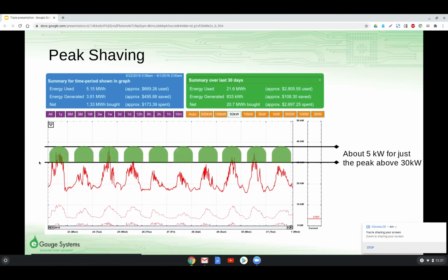When you're designing the system, you can decide whether you want to cover just the peak, where this is probably going to provide the most benefit as far as an ROI standpoint, because you're covering the most expensive energy. And you can customize this depending on what utility you're in, to put in examples of what the actual cost is for these different tiers as well. So in this case, if they only had room for a small system, you can show them that it's going to cover their most expensive energy.